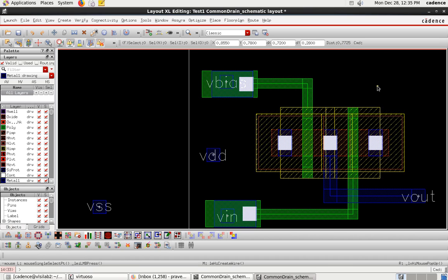If you observe here, this is NMOS, so you can directly connect it to VDD. You don't have to select via N-well, as we did in common source as well as the inverter, because this is an NMOS circuit. For an NMOS circuit, you can directly give the VDD connection because it is not PMOS. If it is PMOS, you would have created an N-well and connected the VDD connection inside that. But here it is only NMOS, so you can directly connect it to VDD.